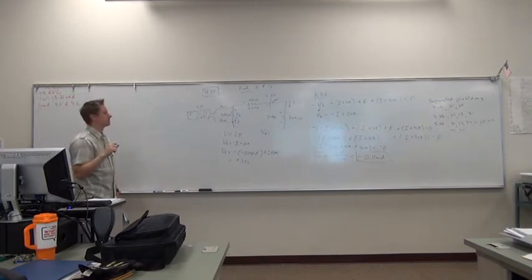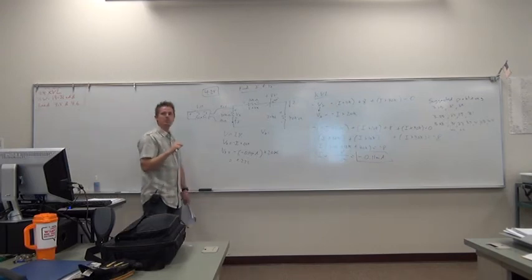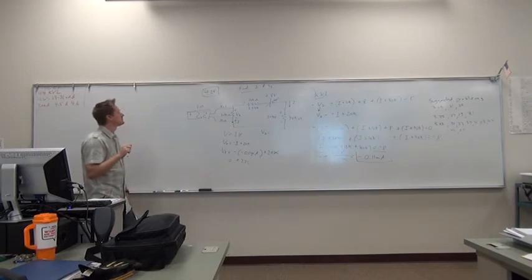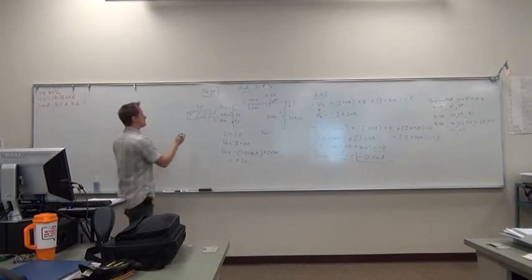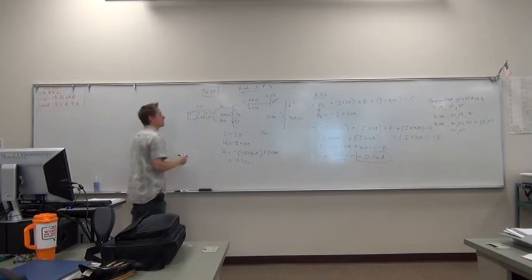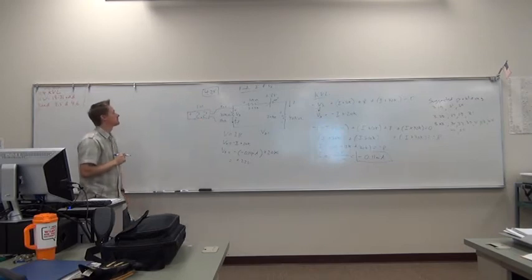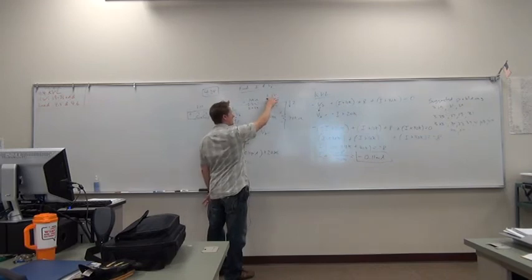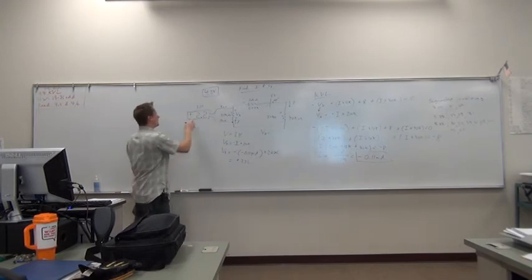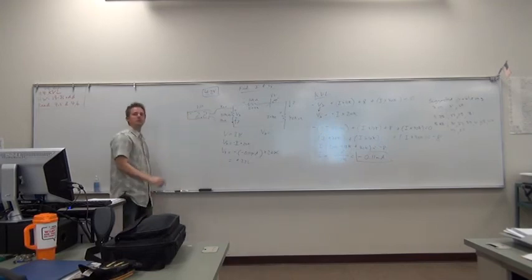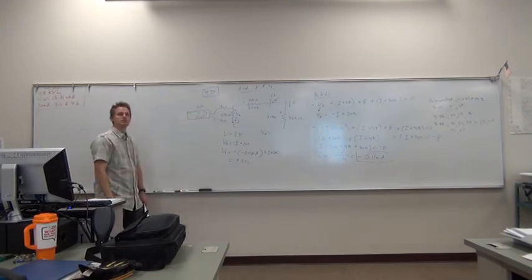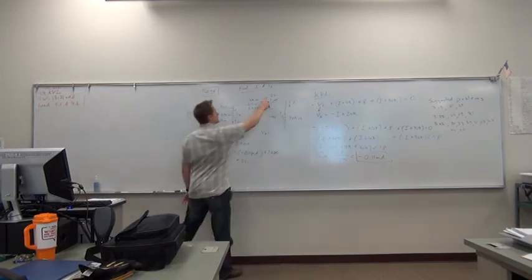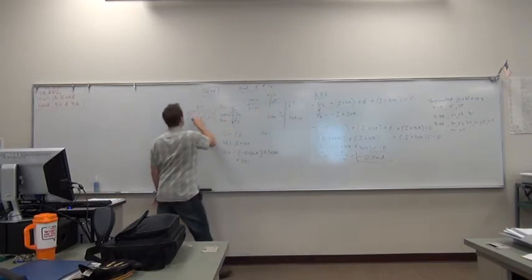So, I'm just trying to put this together. So you say the reference across VA simply is indicating how you hooked up the voltmeter. Your voltmeter, yep. Now if I took this, assuming this is a variable voltage source, if I took this voltage and changed it to minus 8 volts, then I would get a minus 2.2 volts here. Yeah. But in this case, it's plus 8.